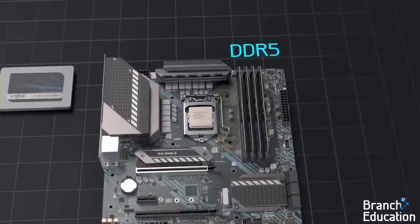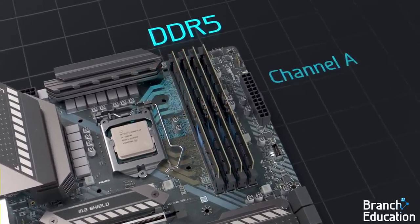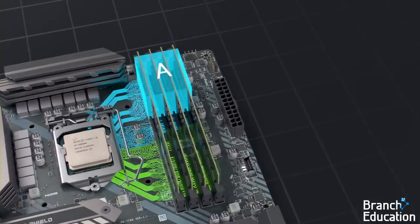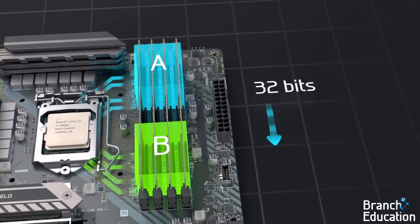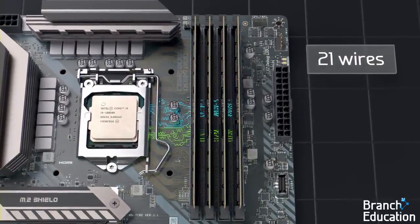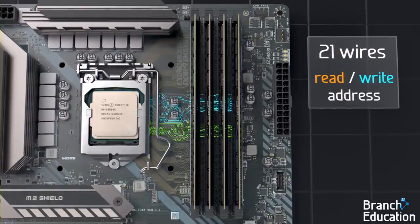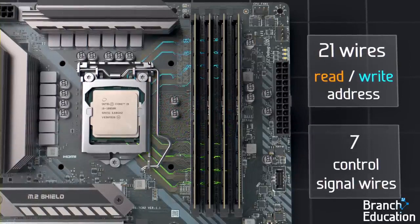Let's move back to see the memory channels. For DDR5, each memory channel is divided into 2 parts, Channel A and Channel B. These 2 memory channels, A and B, independently transfer 32 bits at a time using 32 data wires. Using 21 additional wires, each memory channel carries an address specifying where to read or write data, and using 7 control signal wires, commands are relayed.